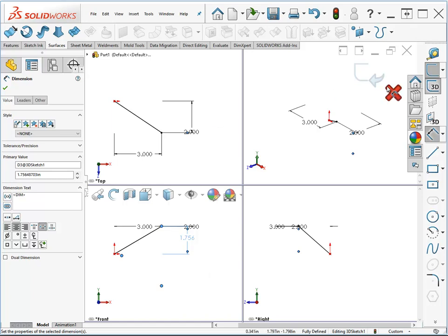Now, you can also create sketch planes within a 3D sketch. I find these to be fairly unreliable. They don't behave like you are used to having planes behave, so I personally leave these alone. And you can have a portion of the 3D sketch on a plane. That's good for times when you need to create things like circles, arcs, and whatnot.